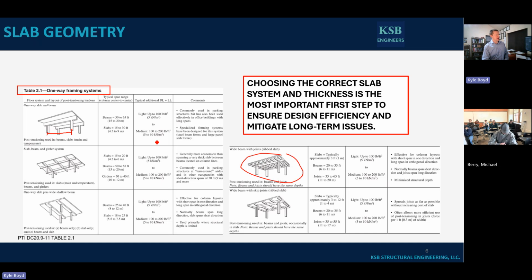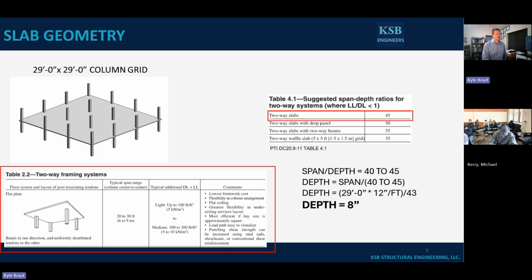And there are a lot of comments of, hey, here's the amount of load that these slabs can take: 100 PSF plus if it's heavy storage. You start seeing these big research and development labs where you need these strong floors, and you'll see more of this waffle slab looking thing in the one-way direction. So this gives you the starting point of, this is the type of slab I'm going to use with this loading on there.